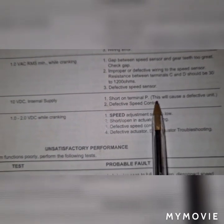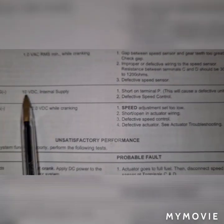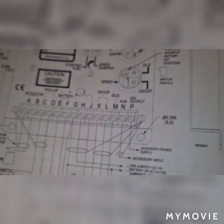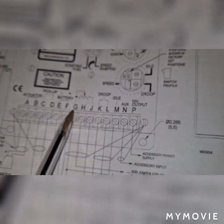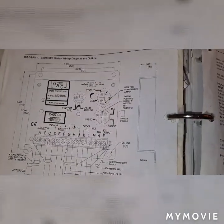A short on terminal P will cause a defective unit, defective speed control. If you have P and G minus, 10 volts internal supply, P and G are connected here. If you measure here, P and G, and have 10 VDC, meaning your speed sensor is defective.